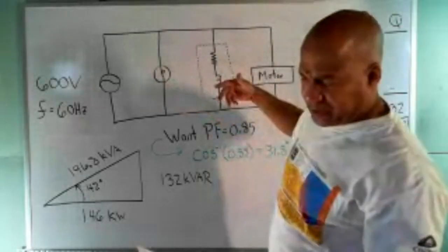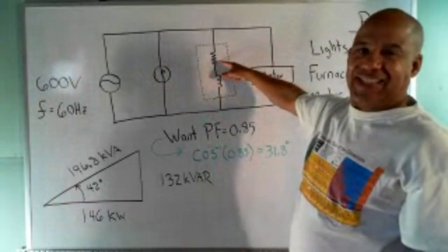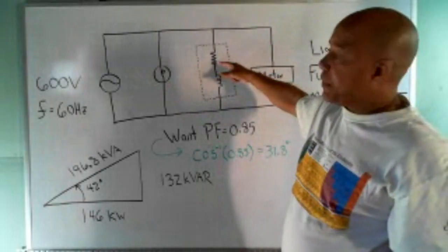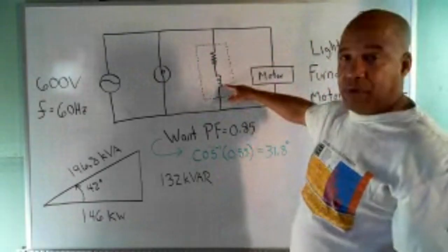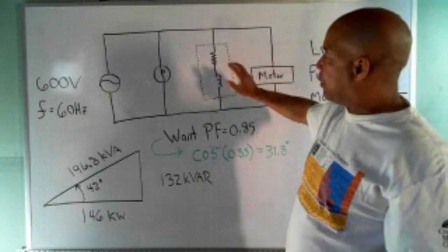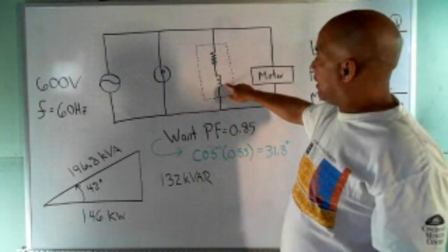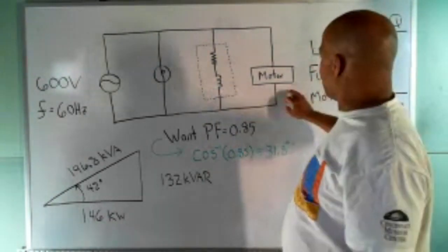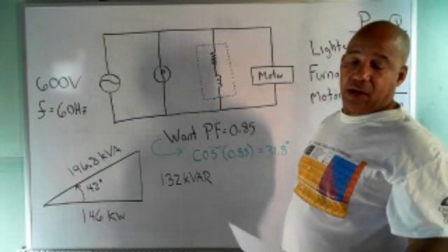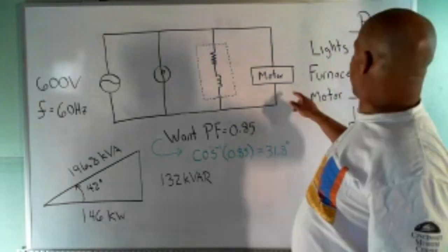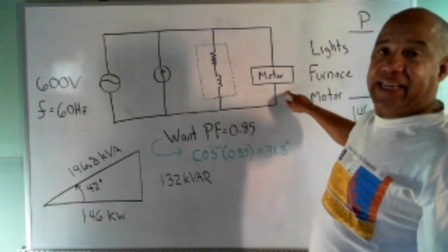I forget what this thing here is. It says electric furnace. So an electric furnace probably has resistive elements that heat up. And then it has a motor like a blower. We have a reactive element to it, so we can model that as a wire resistance, R sub W, and then the reactive component. Then there's some kind of motor, and for the motor they did something interesting. For the motor, they told us it was, I don't have it on here, but it's an 80 kilowatt motor. It's an 80 kilowatt motor.